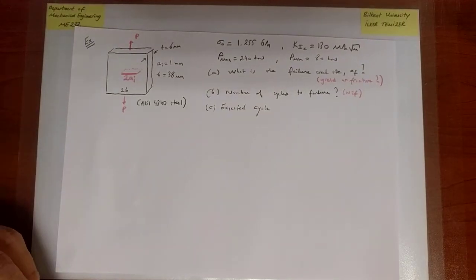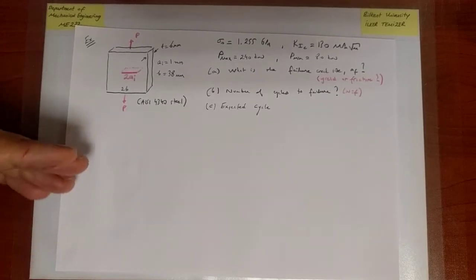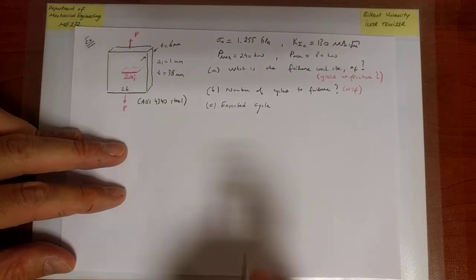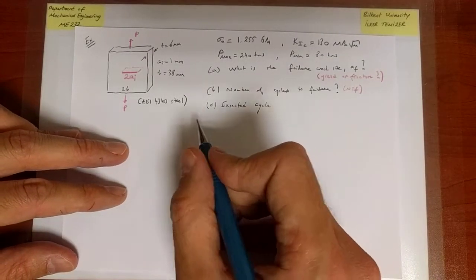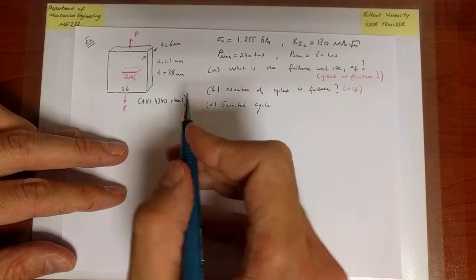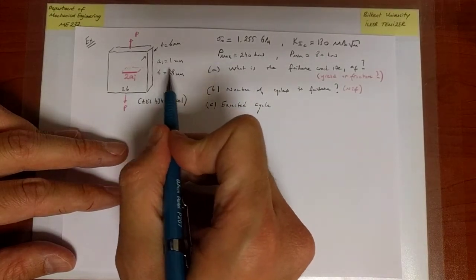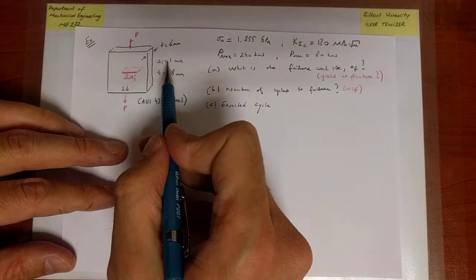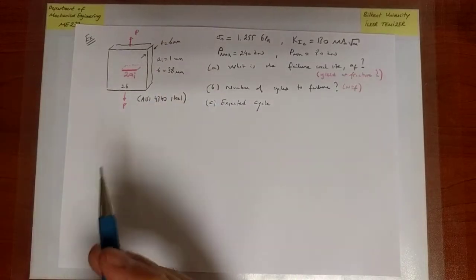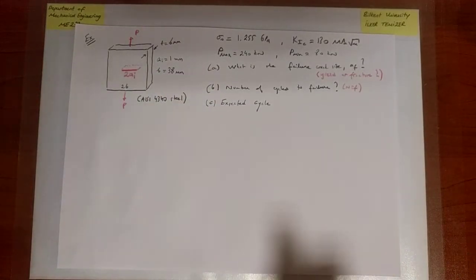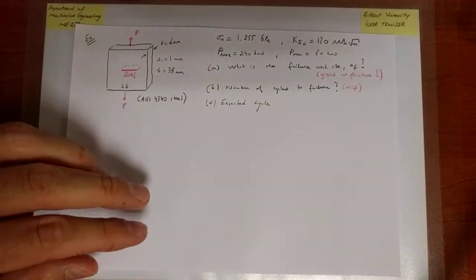I need to assume that the cracks that are smaller than the minimum detectable crack size are actually somewhere in the structure. And I will be provided with the fact that for the context of this example, the detectable crack size, minimum one, is actually the initial one. Okay, so a_i is simultaneously going to be the detectable crack size for the purposes of part C.